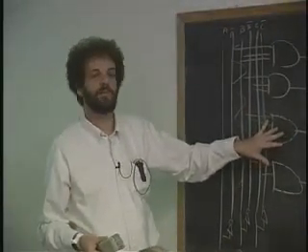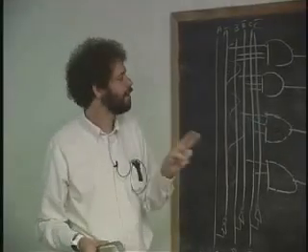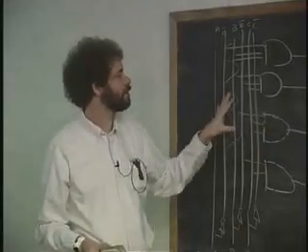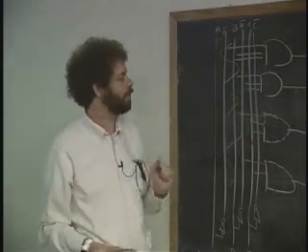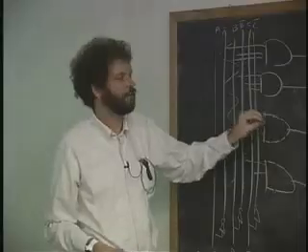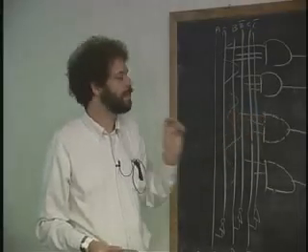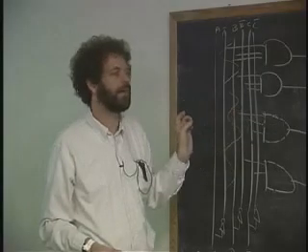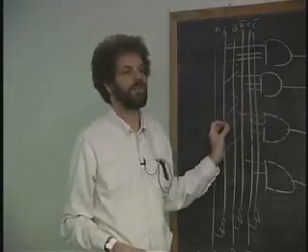Okay? And you know what's even worse than 2 billion AND gates? Two really awful things. A lot of those AND gates are hooked up to the same wires. And it turns out, and we're going to talk about the physics of this, that the electrical characteristic of these AND gates loads the wires just a little bit. Sensing the 1 or the 0 on a wire involves transferring a little bit of charge into or out of the AND gate.